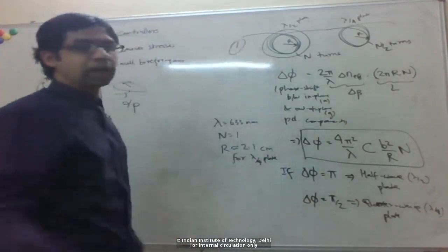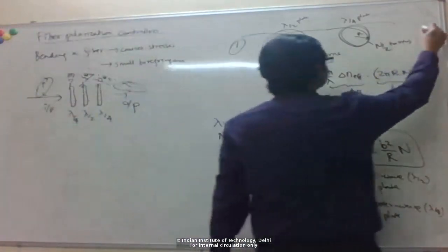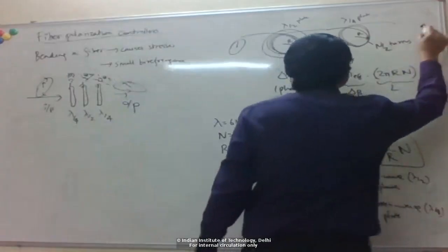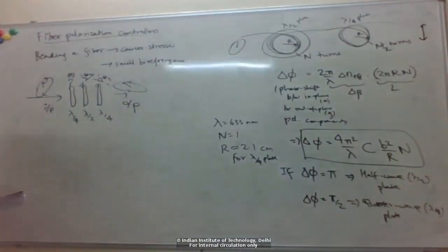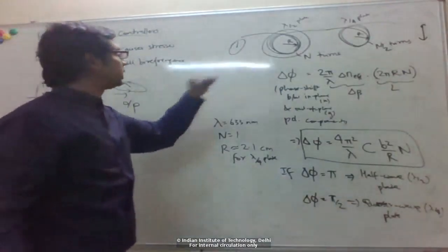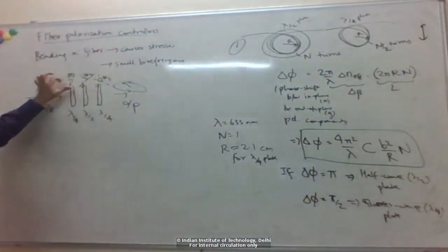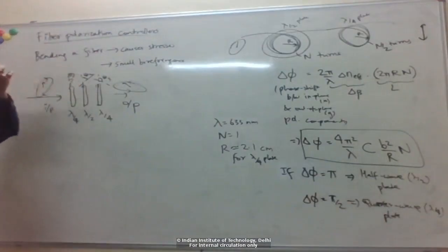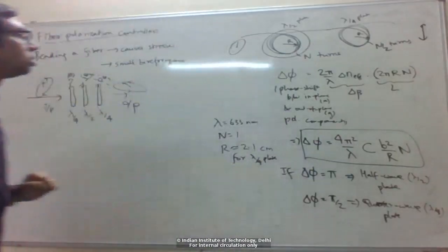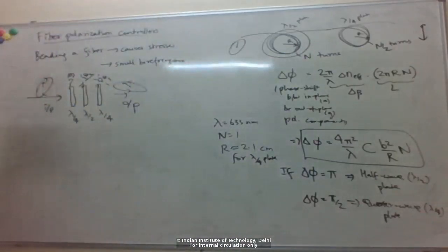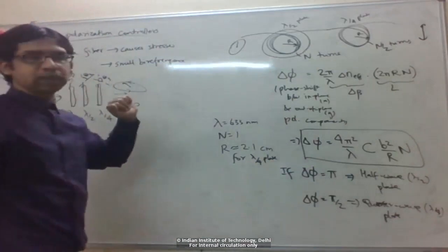But let's say for your application, what you want is the output polarization to be linear. So what you do with this device is manually adjust these angles θ1, θ2, θ3 until the output polarization becomes linear. You don't know what the input polarization is, so you keep adjusting these angles and keep measuring the output polarization.